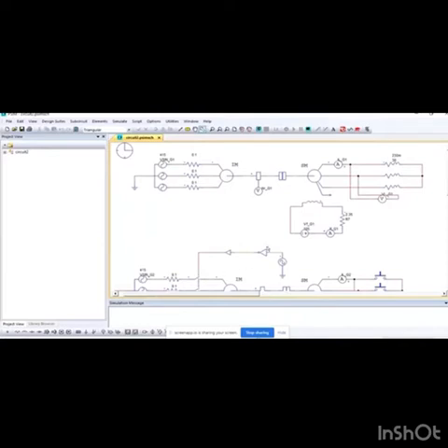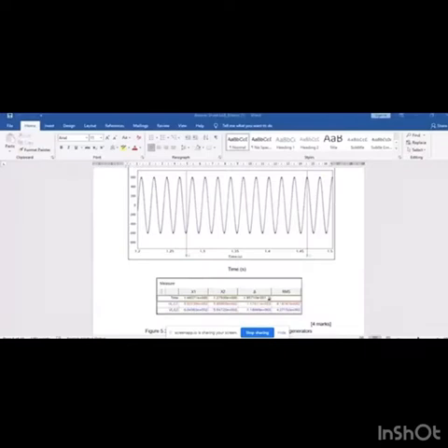For the 5.2 we set the resistor to 30 ohm and for the inductance we set 230 millihenry. For both generators we set 51.0 Hz. Question 1 asks for the waveform of the line voltage of two three-phase synchronous generators for the time 1.2 to 1.5 seconds. After that, we simulate the circuit. So this is the waveform of question 1. It asks for 1.2 seconds until 1.5 seconds.